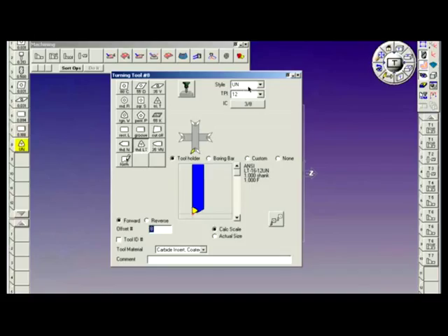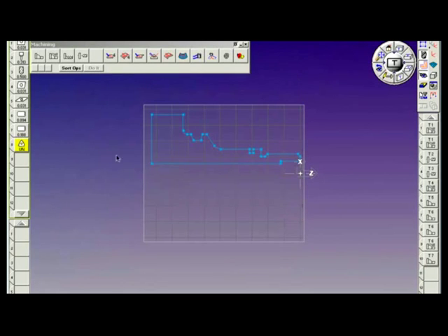The style is UN as opposed to a UNJ and ISO and NPT, ACME. You've got a series of options here. Go with the standard UN class. Threads per inch based on our blueprint was 12 threads per inch, and the tool is defined in the viewport. Close the window, bring down the tool and the threading tile.